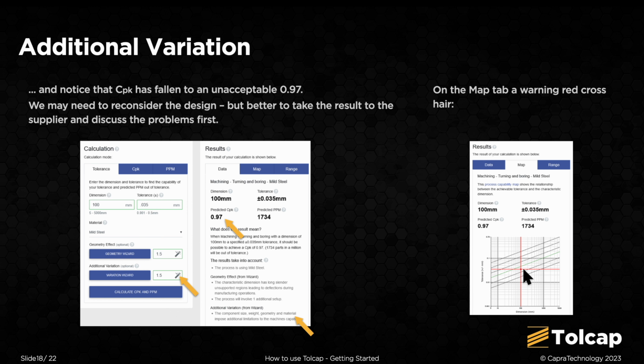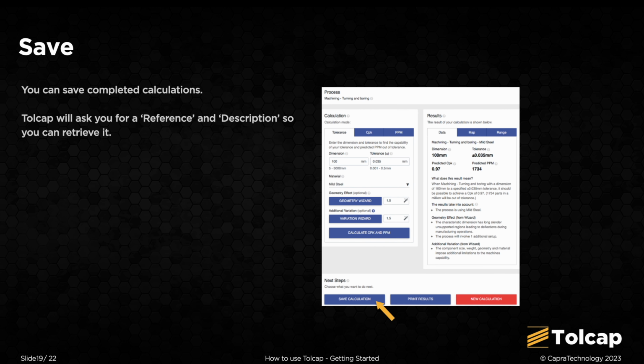Okay, the part is near machine capacity. Is that a real problem? Does it matter? Is there a similar sized part in production? The part is long, but can it be propped in the middle or maybe held in some sort of collet so that the part is supported and the problem eliminated? Positive answers here, backed up with data from the process on similar parts, will allow us to go back to the analysis and get a better prediction.